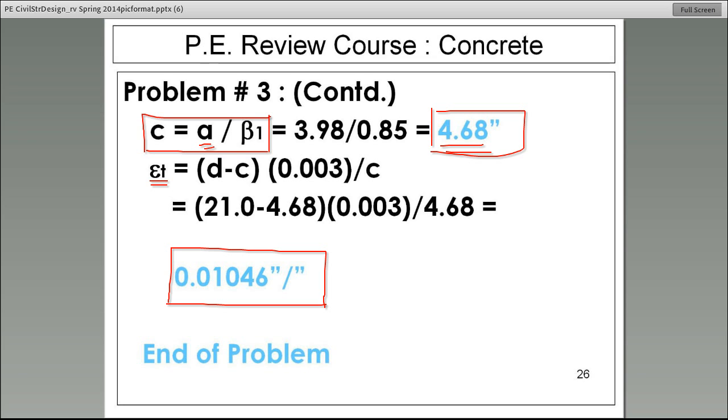Christopher says we want to make sure the steel reinforcing yields before concrete fails. All right, guys. Ryan says we want steel to fail because it will yield and give us warning before it fails. And that is, most of you said it correctly, those of you who said steel, all right?